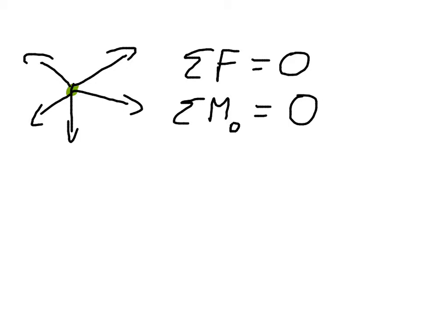I'll try and draw a couple here though. So for instance, the sort of detail you may be asked to distinguish between is that. On the left hand side we have a rolling joint, and on the right hand side we have a pin joint, and the rolling joint is a bit like a roller skate. If I push down on it, then it will push back up. If I push it in the X direction, it would just roll. There'd be no reaction force, so there's no support, there's nothing to stop it moving in the X direction.